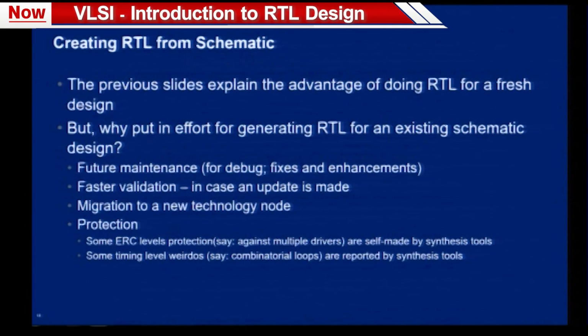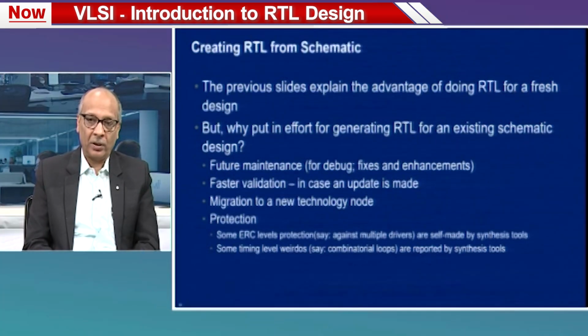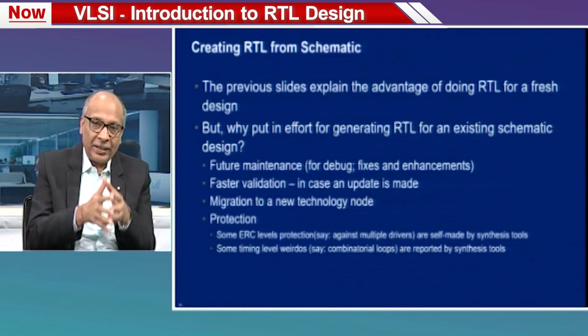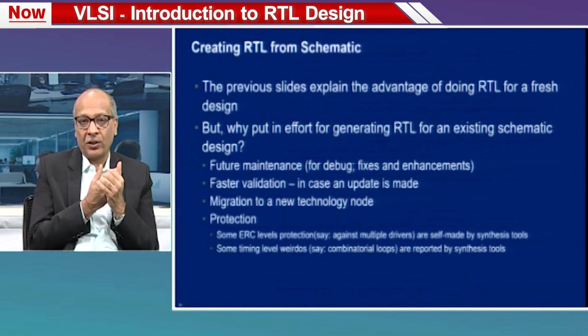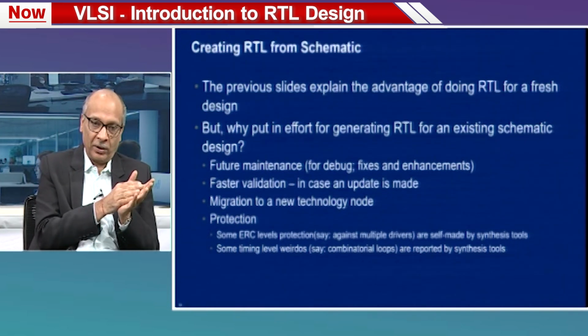So, now that we know that RTL based design is a better style, right? We have seen the advantage of RTL based design, and we know that this is a good style. What if I already have a design which is done in schematic form? Should I convert it into RTL or not, so that I can get the advantage of the RTL? So, fresh design is very obvious. For a fresh design, you should always go with HDL based, RTL based style if possible. But if the schematic based design already exists, should I make an effort to convert it into RTL? Okay.